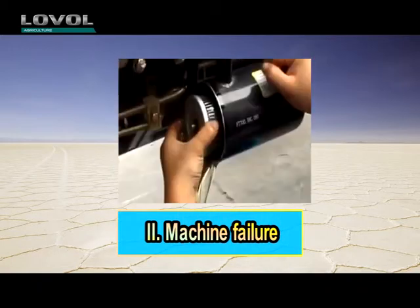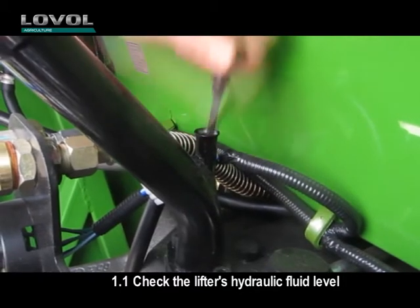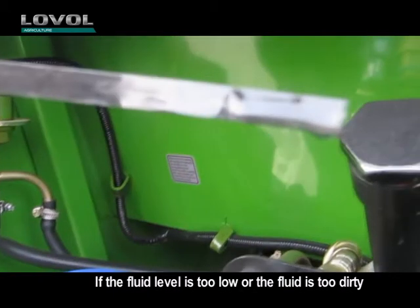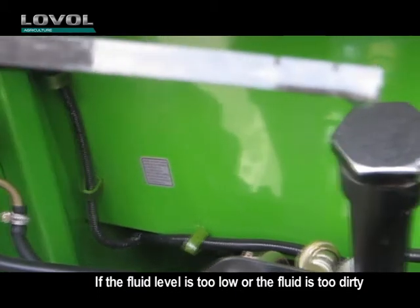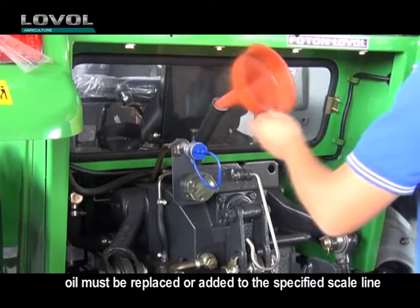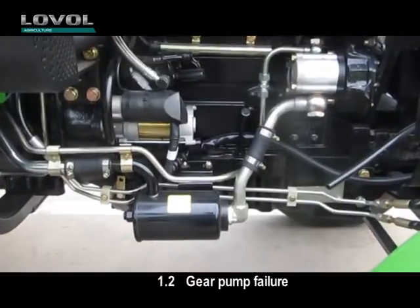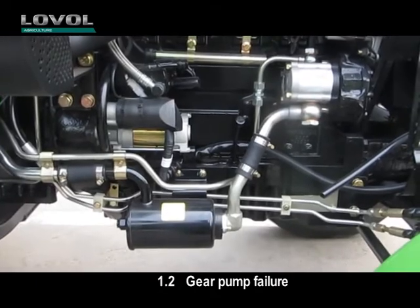2. Machine failure. 1.1 Check the lifter's hydraulic fluid level. If the fluid level is too low or the fluid is too dirty, oil must be replaced or added to the specified scale line. 1.2 Gear pump failure.